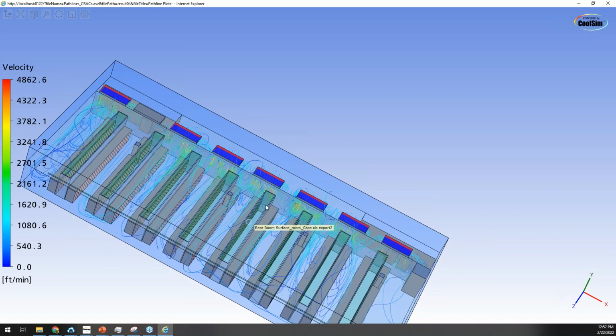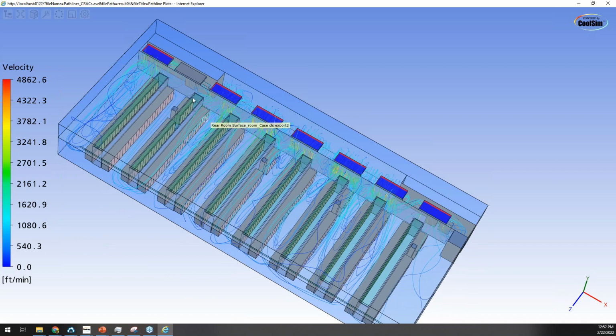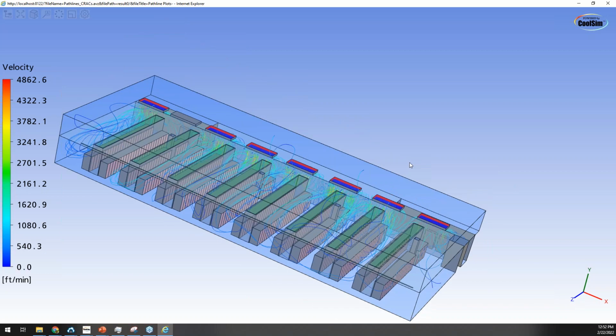A lot of people will simply do the algebra and they'll say, oh, there's plenty of air in the room, we're all set to go. Not so much. If you lose one, another unit, like this one, has to supply air over to satisfy the needs of this rack. To do that, it's got to get the air over there. There's lots of blockage in the way. And furthermore, it needs to pull the hot air all the way back across that room. And if the ceiling is leaking, then you lose that pressure gradient to pull it. And it just goes up and fills the ceiling.